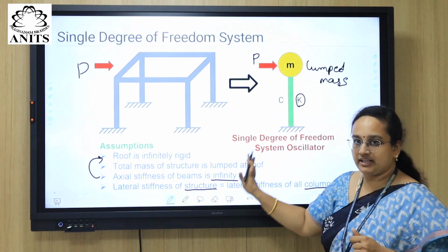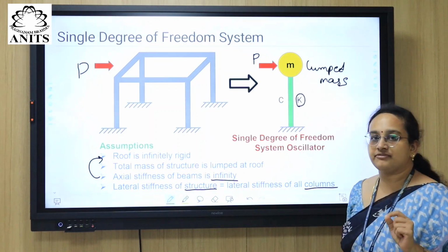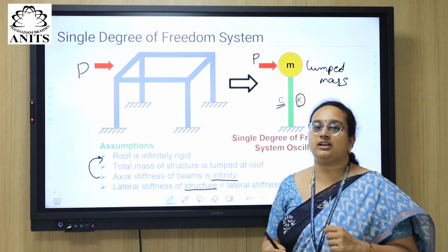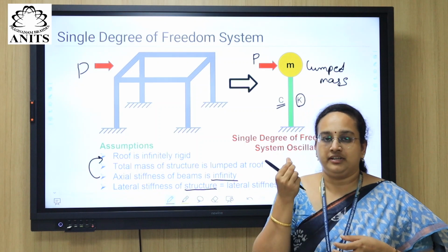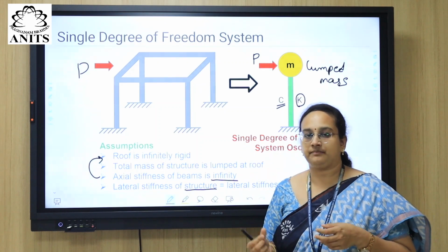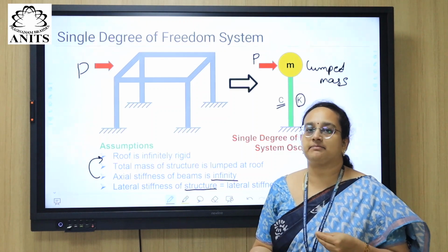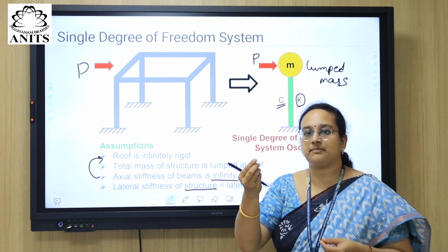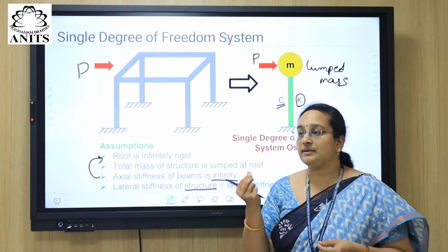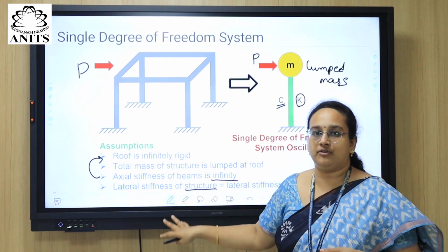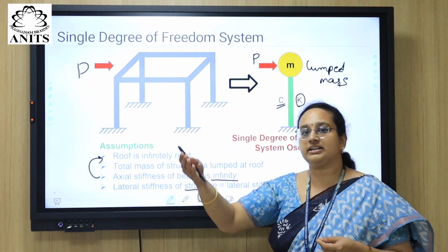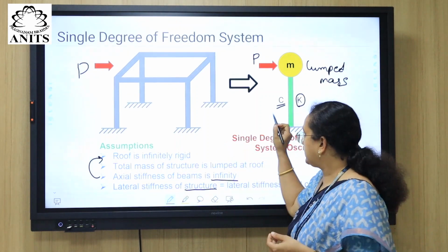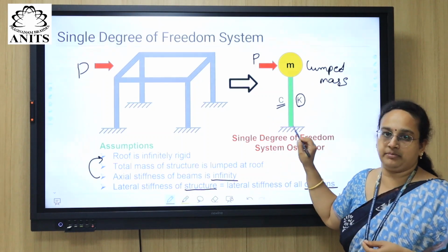Okay, how do I arrive at that? That we will discuss later. But K is the stiffness parameter. And then there is another parameter called damping. Damping is majorly caused because of the particle-particle friction, right? So with particle-particle friction, whatever material it might be, RC, it might be steel, at molecular level particle-particle friction will be there. That will develop some form of resistance to whatever kind of force that is being applied, even if it is lateral force or transverse force. Whatever might be the force, there is some resistance offered from the material. That is actually accounted for in the damping, right? C.